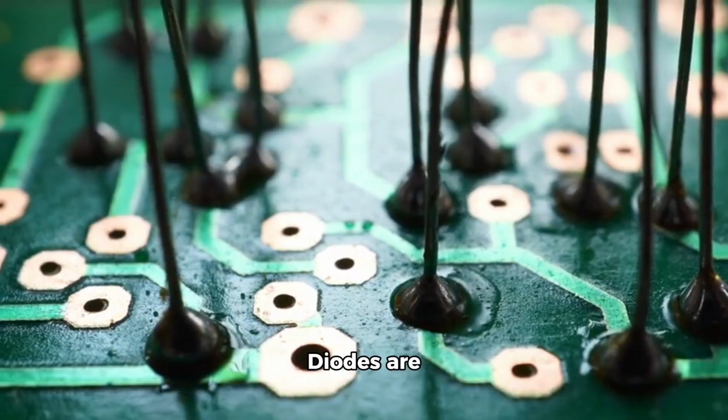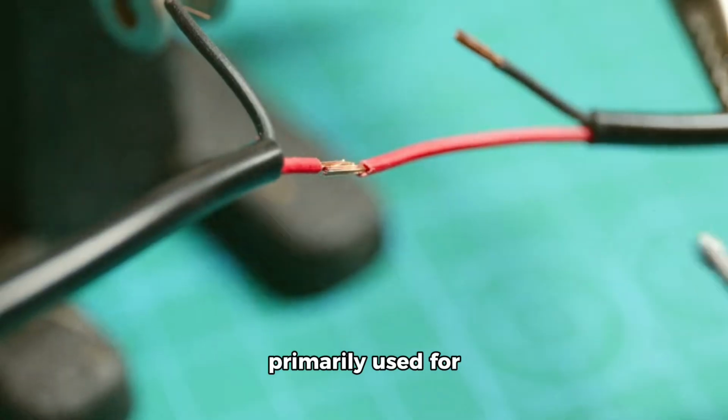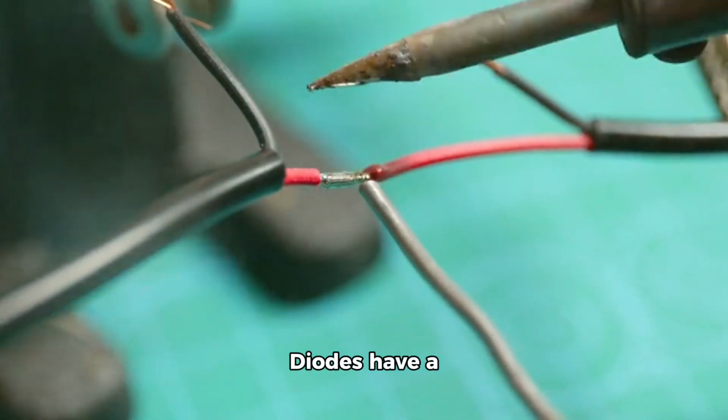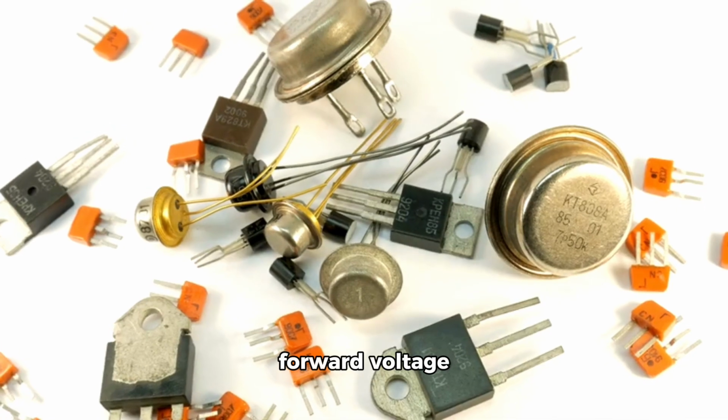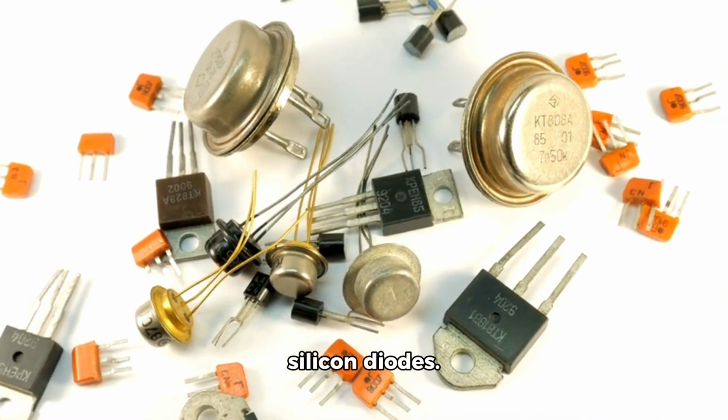Diodes are semiconductor devices that allow current to flow in one direction only. They are composed of a p-n junction and are primarily used for rectification, converting AC to DC. Diodes have a forward voltage drop, typically around 0.7 volts for silicon diodes.